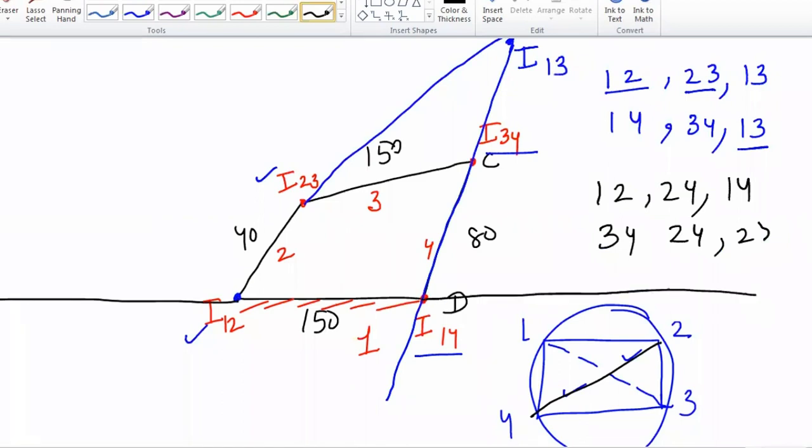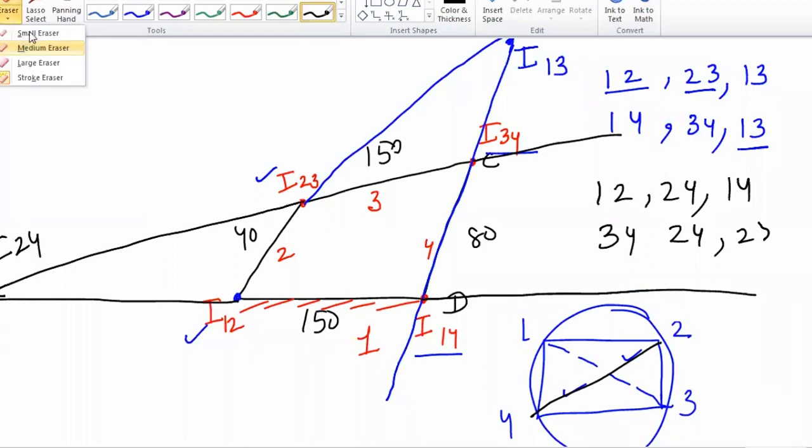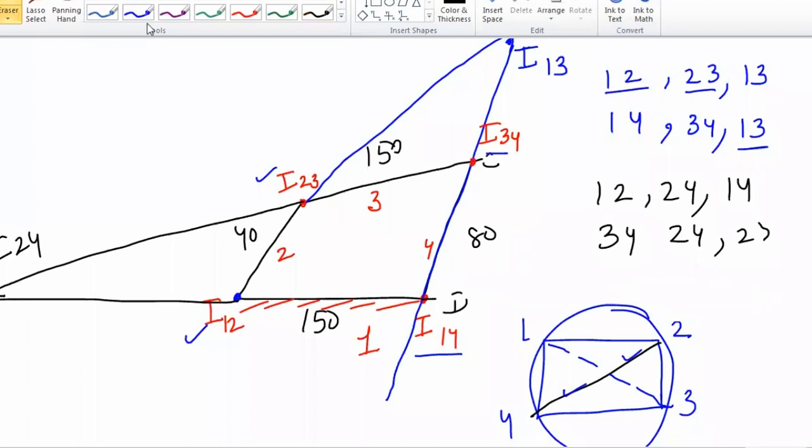On this straight line, the 2 4 is coming out to be. Similarly, 3 4 and 2 3 we also know. So this straight line will give you the I24. Let us extend up to here. That intersection point will give you I24. That is pretty easy, na? Simply extend this line. Extend this line, and you will get to know what is the I center location.